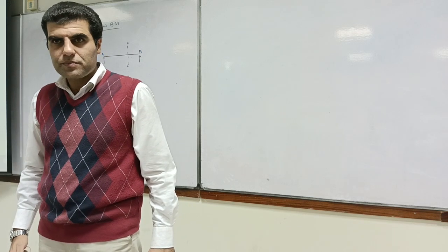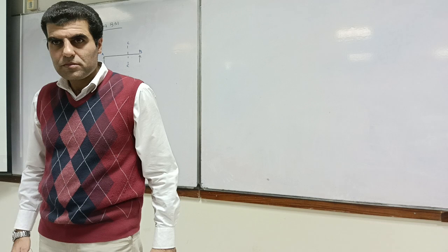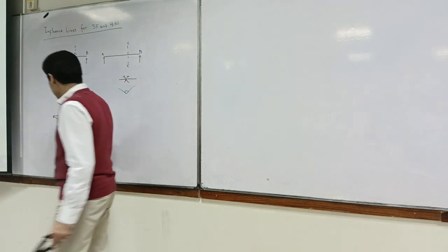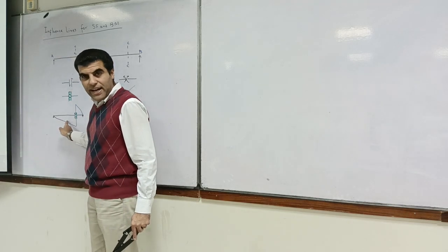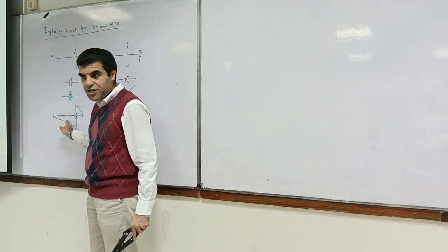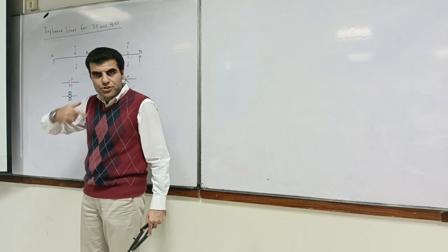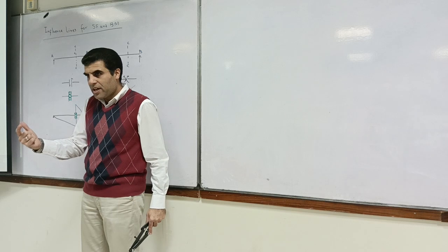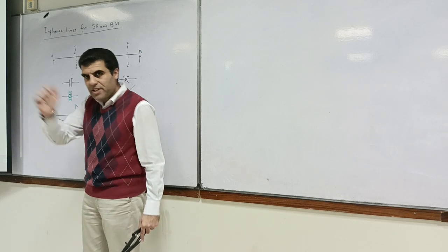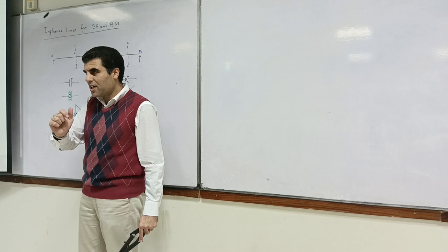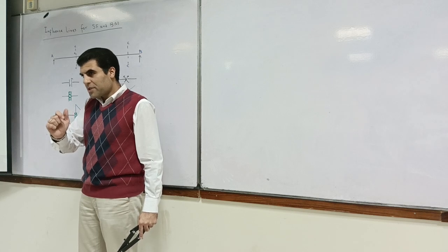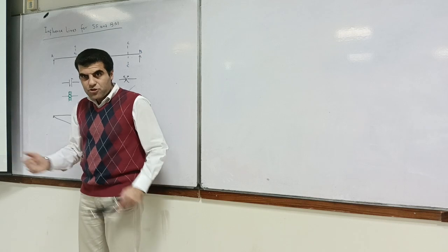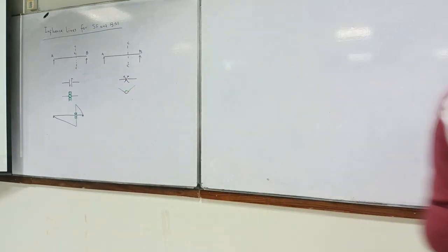Sir, but I was assuming that there may be some longer side or something. What do you mean? The longer side doesn't have any influence on the shear. Okay, sir. The side length doesn't have any influence on the shear. Shear is always the summation of all the forces in y direction towards, normally, the left we take. So all the forces which are in y direction towards the left of a section, and all the forces which are towards the right of the section. Yes.